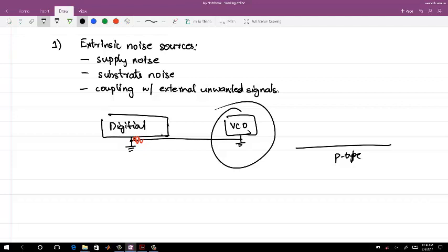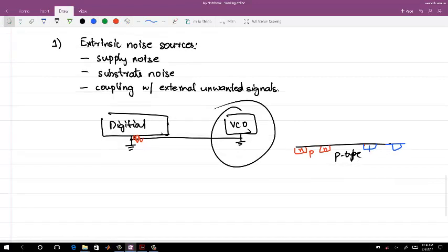Means for NMOS you will have an NPN, and for PMOS you will have a PNP. Means you will change the other part. But they're all made on the same wafer, right? So there are ways where you can create a deep well around NMOS MOSFETs.